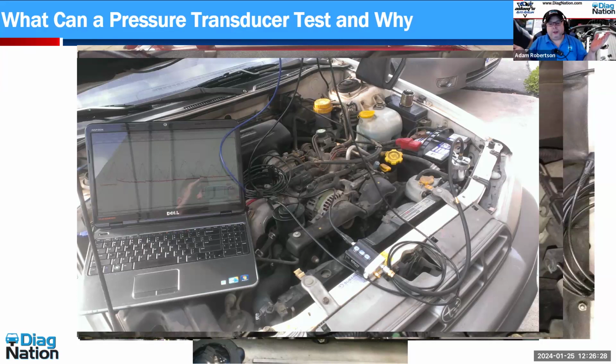That's kind of cool. But then I got the chance to test a car. It was probably a BMW or an Audi. I don't remember at this point. But the water pump impeller had fallen off the water pump. And many of you listening to me have been through this, all right? I was revving the engine up and I didn't see that camshaft-like waveform from the coolant. It didn't change. I'm like, this is kind of weird. They go, yeah, that thing's here because it overheats. And I'm revving it up and I'm like, whoa, I think I found an easy way to see if the water pump impeller's working. And sure enough, the water pump impeller had fallen off.